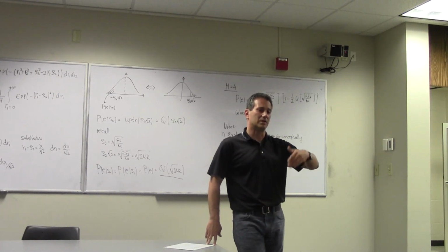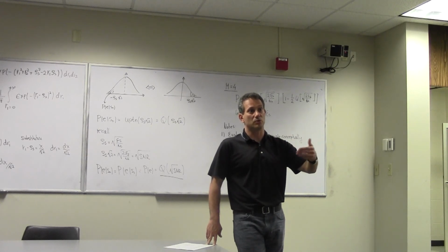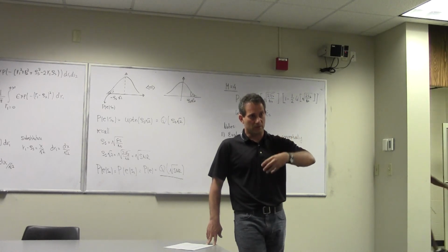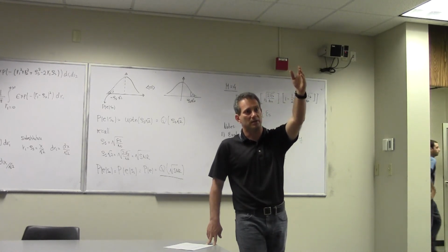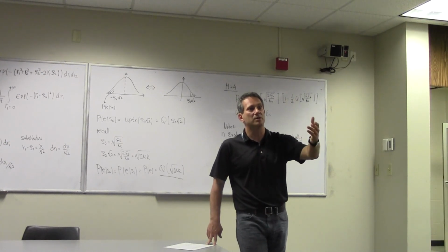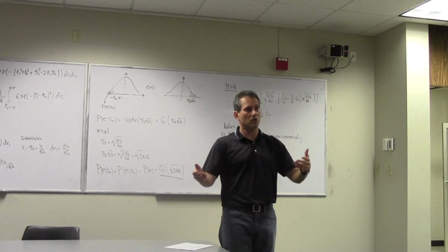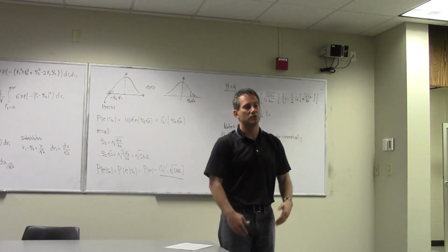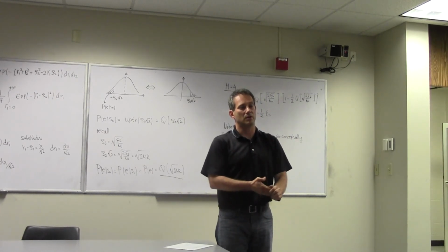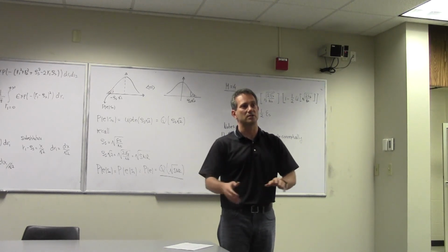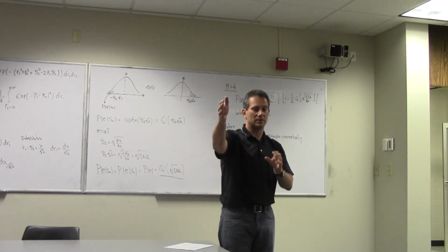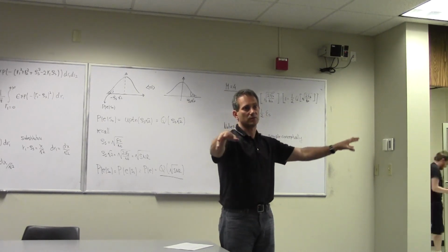If you look at even further detail, there's always what we call a measurement report of some sort, or channel estimation report, where the mobile or the receiver sends back to the transmitter feedback saying, this is how good my signal-to-noise ratio is, and this is what I recommend that you use for the transmission. And then the transmitter says, oh, okay, so here's higher throughput, right? Because it benefits the transmitter too, especially in the case of multi-user access, because then I can deliver all the data to this guy and free the resources for all the others.